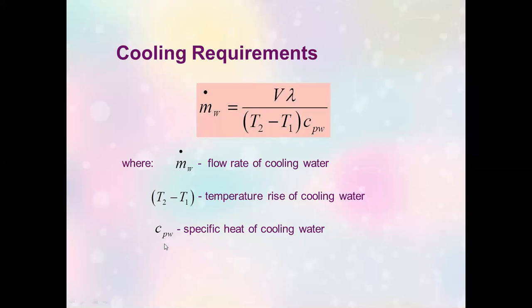There is this problem in heat transfer that when we speak of the condenser, the CP that goes with the difference in temperature is based on the average of these two temperatures. But the difference in the answer, whether you base the CP on the average of these two or on just one temperature, the room temperature, is very negligible. So for things to be a lot simpler, just base it on the standard CP of water, and then multiply it with the difference in temperature.